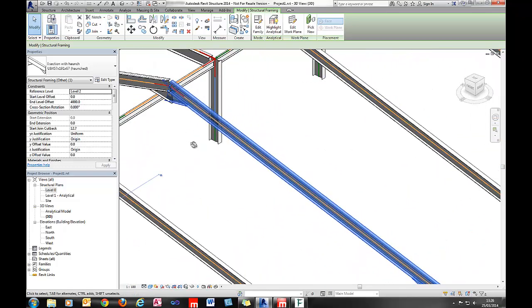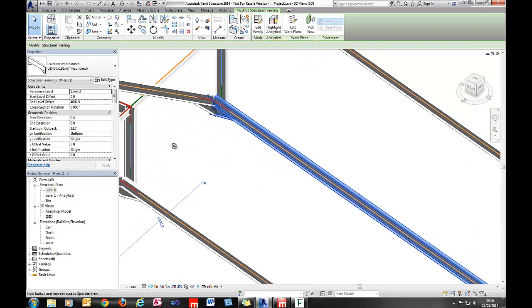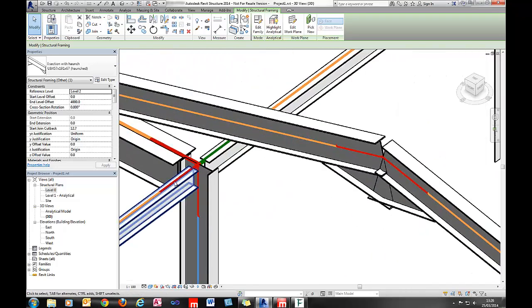I mean, the Revit default for the alignment of the physical member with the structural analysis line for beams, as we can see down here, is that the analytical line would be at the top of the section. And clicking on that, that's controllable. Obviously, you can say for that section that its justification is to the top of the section, basically in these areas here. So you've got your Z direction justification to the top here.